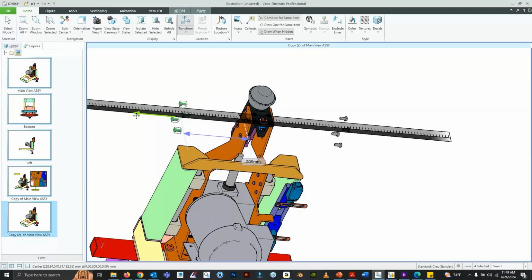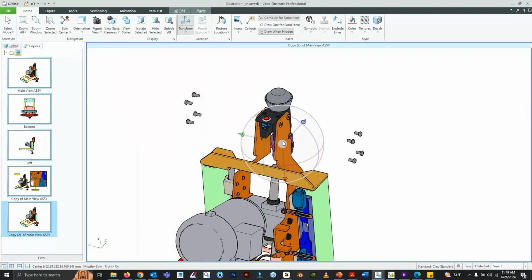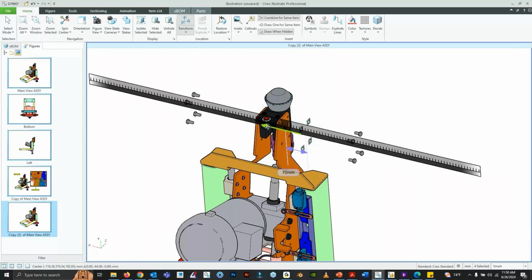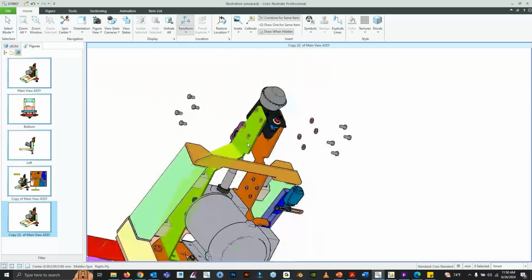And you can see it's got the number value down there. And I'm holding control to get this ruler to show up. Same thing with this. So you could just easily start taking all these components and just start dragging them out to get your exploded view. And I'll do these ones right here.